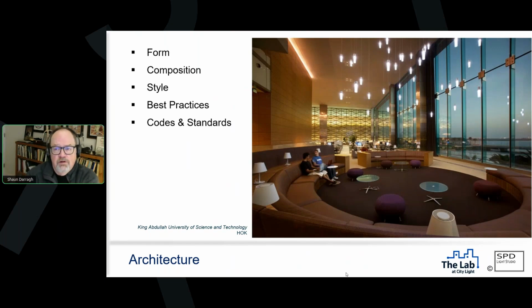Now, when we were building this, the contractors didn't want to put that up there because they felt that we were gilding the lily, as they kind of put it. But afterwards, when we had them look at the space with that one little line of light turned off versus one little line of light turned on, that made an enormous difference in how people perceived the brightness of that space, because it had a little bit of glow within your field of view that separated those two planes, and for a very small amount of energy, really tied the space together, okay?